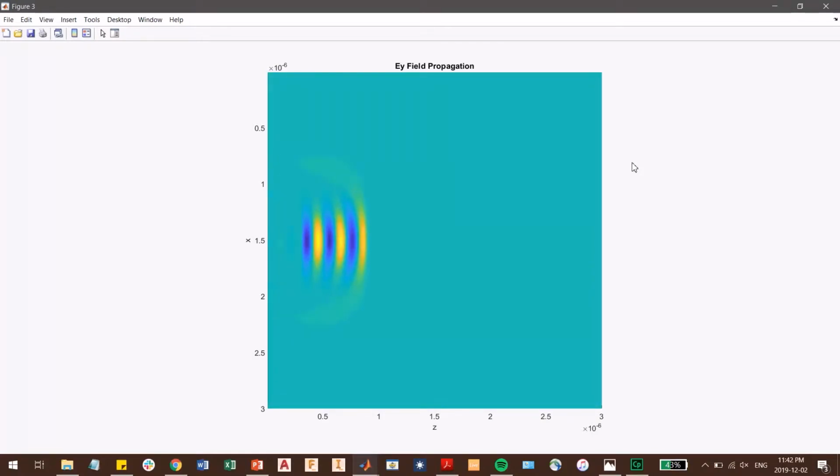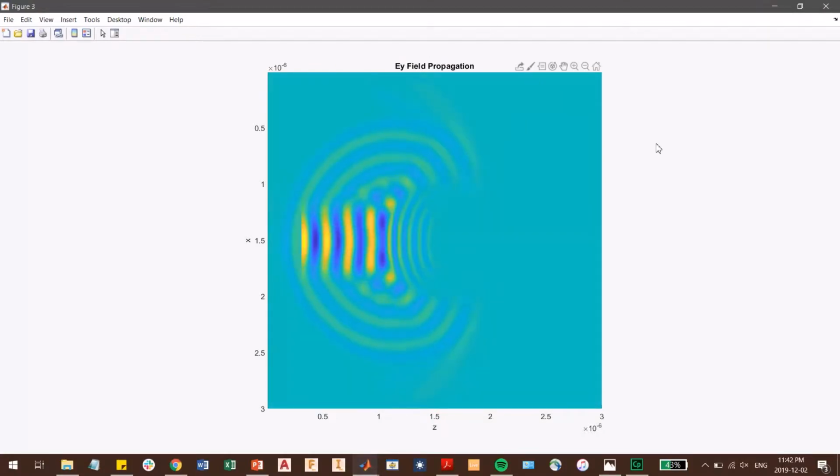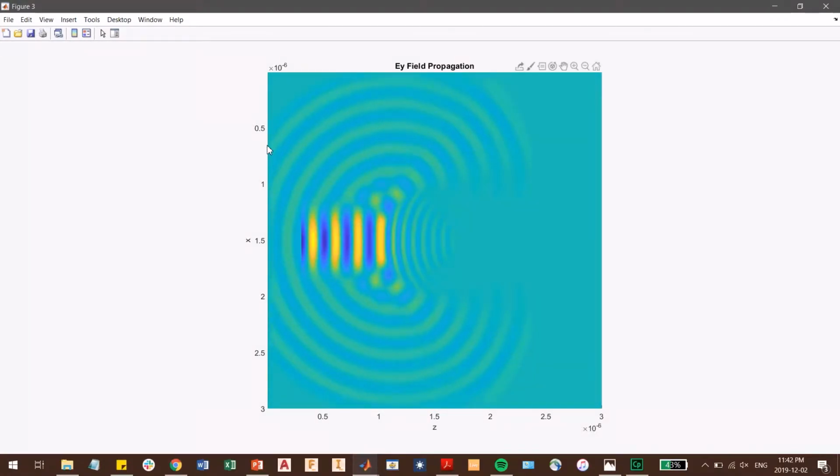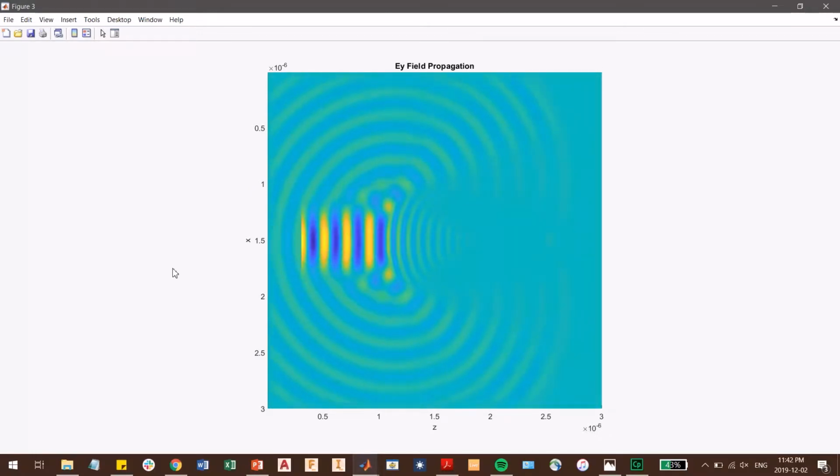However, we'll likely see more of the waves as they reach the edge of the space here, as the gradual layer won't attenuate them as immediately as the sudden PML. Yeah, we can almost see them go right to the edge here, but we still are getting no reflections, so the boundary layer is performing well.